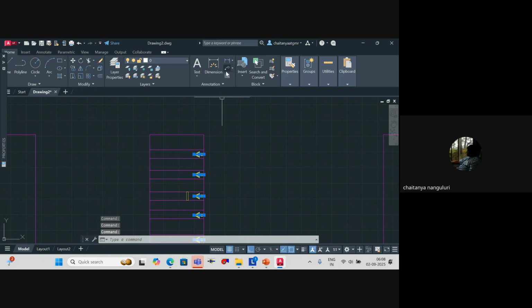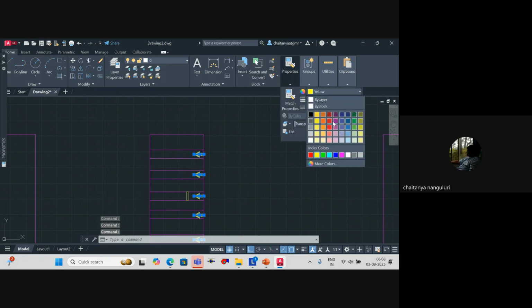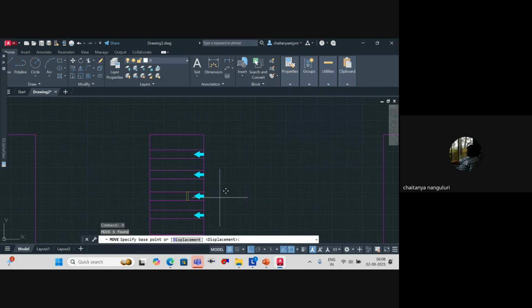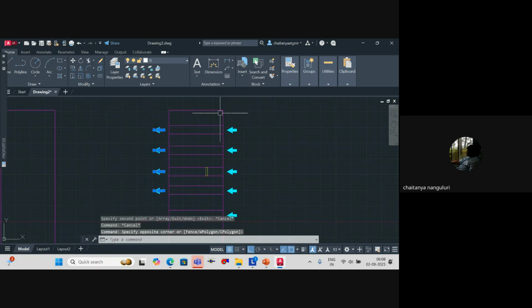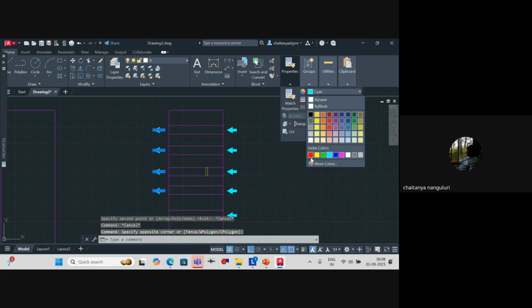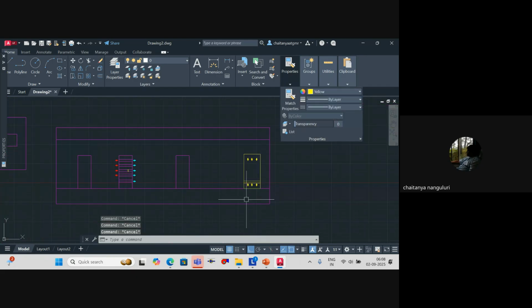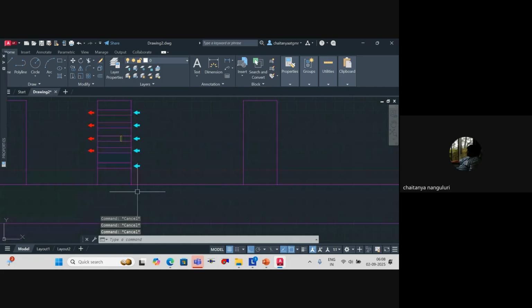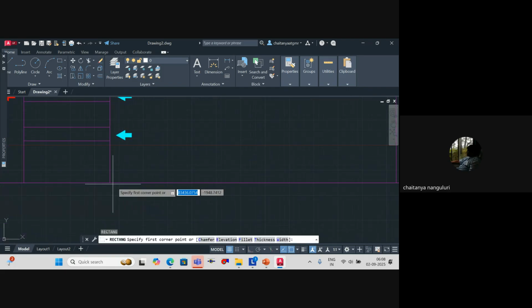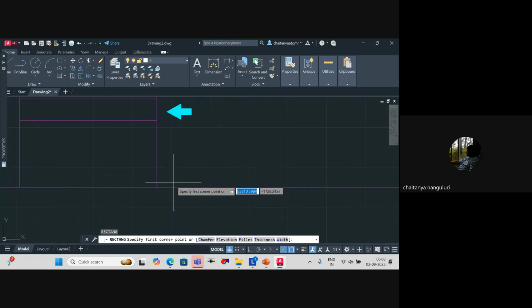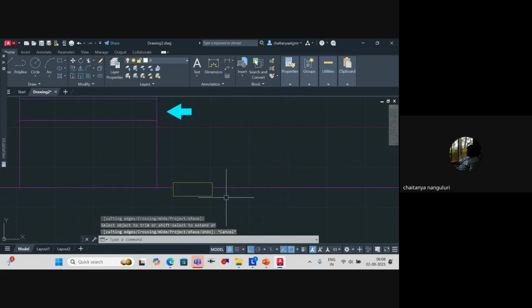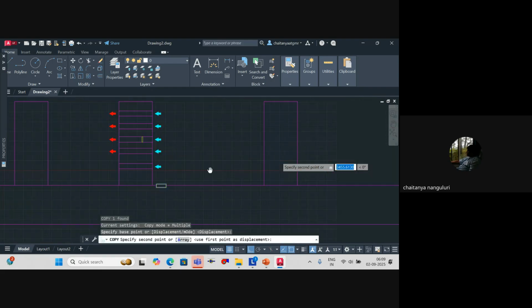So let's say this is your air that's entering, and again this is your air that's leaving after heat exchanging. What we do here is we place something called floor grills at these locations. Just in front of its suction, wherever it is, you provide floor grills. Understood?